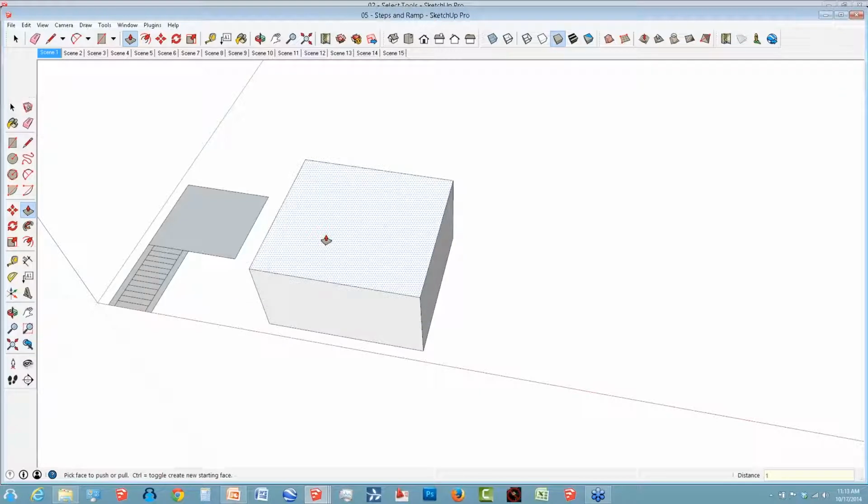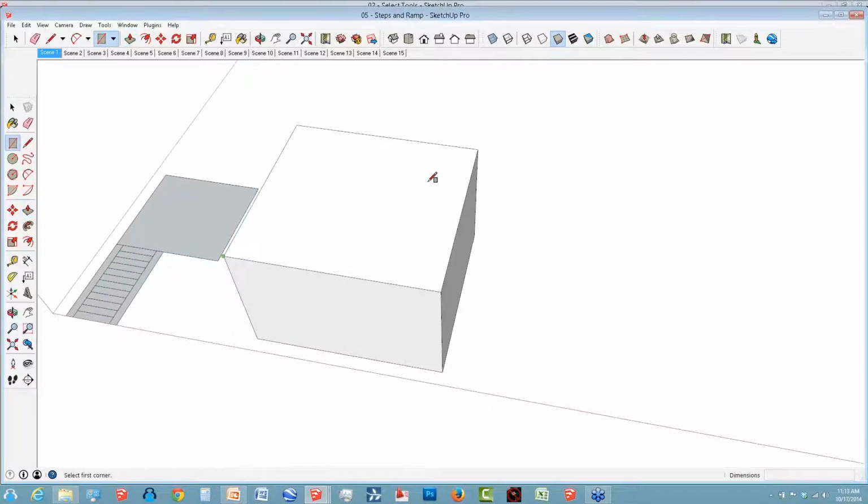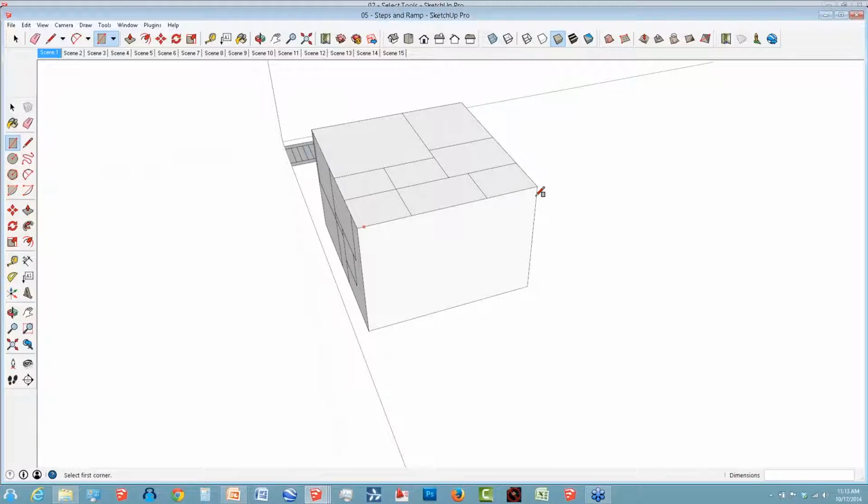So there's a whole measurement system in SketchUp that allows you to accurately enter dimensions for line lengths, for extrusions, for moving and copying objects, rotating objects. Everything you're doing in SketchUp is always going to be somewhat parametric in terms of adding values to it. And this works particularly well because one of the things you're going to do often is import your CAD drawings from various CAD sources, which are going to be accurate, measured, drafted line work.